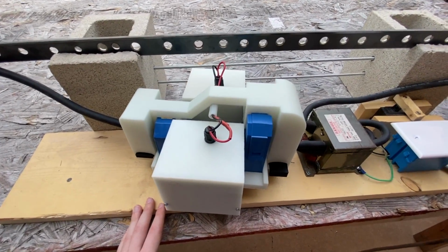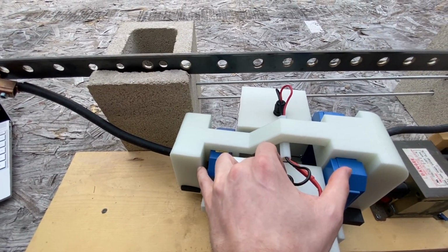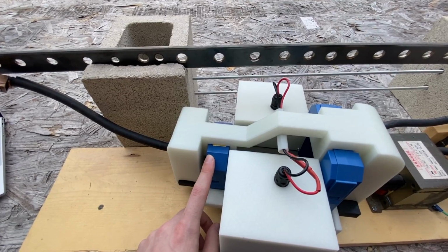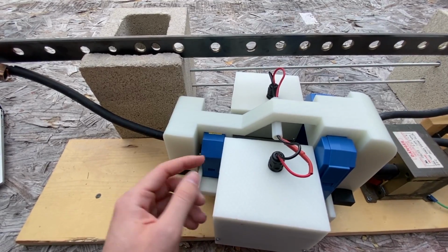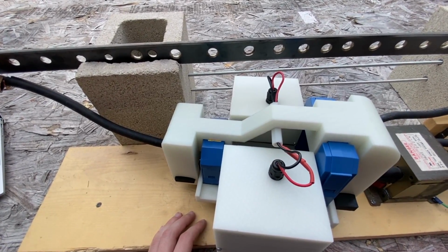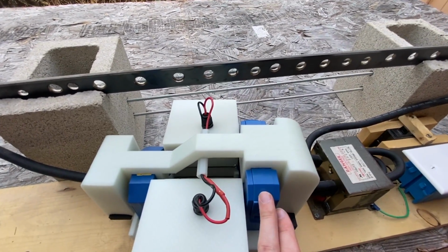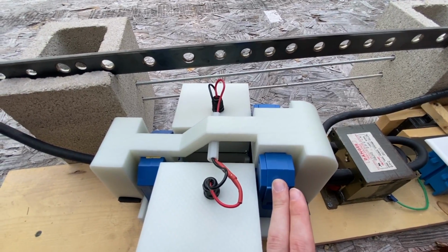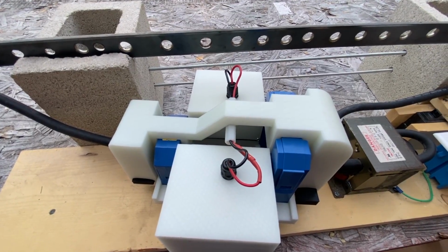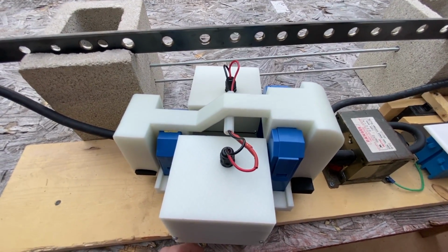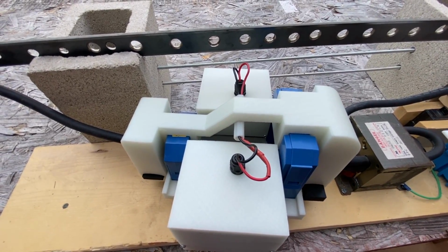So the way that this works is we have two current transformers. This one here is used for sensing current, and that current is measured by a microcontroller. The microcontroller also handles the temperature and humidity and acceleration data. This current transformer here is used for powering everything, using some power electronics. And then there's also a battery backup that can power the system in the event of a power failure on the line.